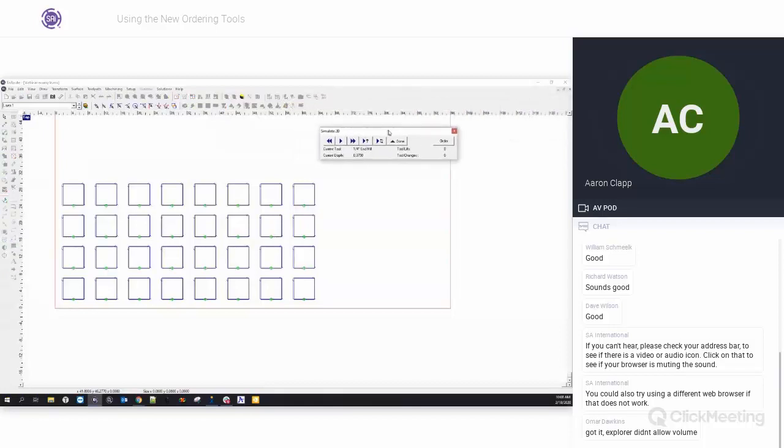So I'm going to click on simulate. I'm going to bring this over here. I'm going to click on my order button. And the important thing here is going to be that we set the object order as number 1. So this can be a little bit tricky, but if you guys have never moved these things around, the trick here is that you want to click on this little box next to object so that the black arrow is pointing on it and that it's highlighted blue.